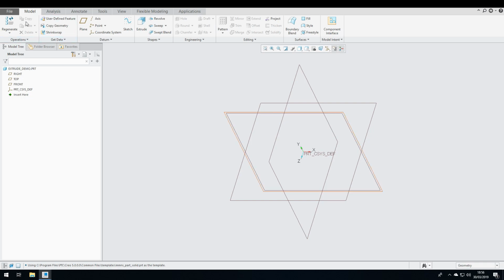So in the top ribbon here you have all of your features, so you can create a new plane. There are three standard planes, your X, Y and Z, that all cross through 0, 0, 0. You could add a new plane so you can offset it. If you know you want your drawing to start somewhere else and extrude through it, you can do it that way. That's what the plane function will do, and you can set planes at angles. If you want 45 degrees between that plane and that plane, like a bisector, you can have that one. It's useful, I'll come on to that later.